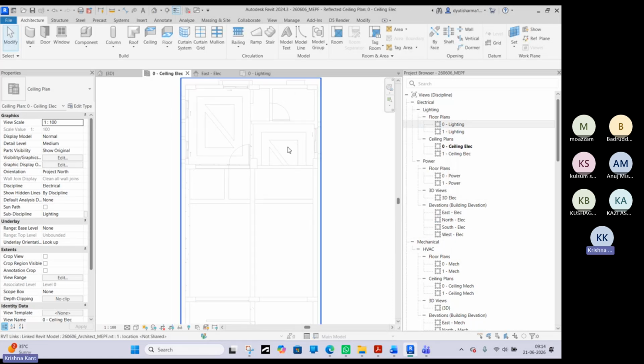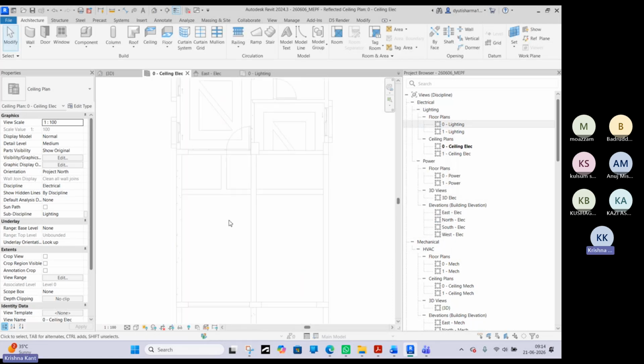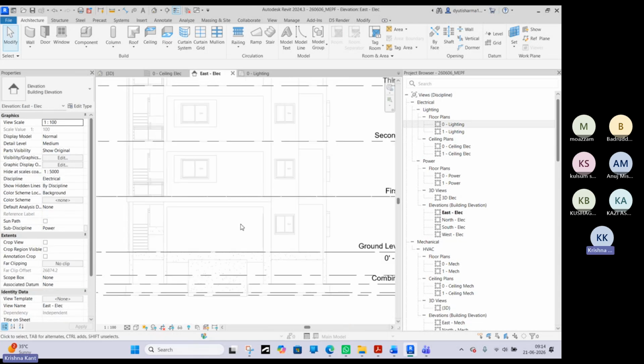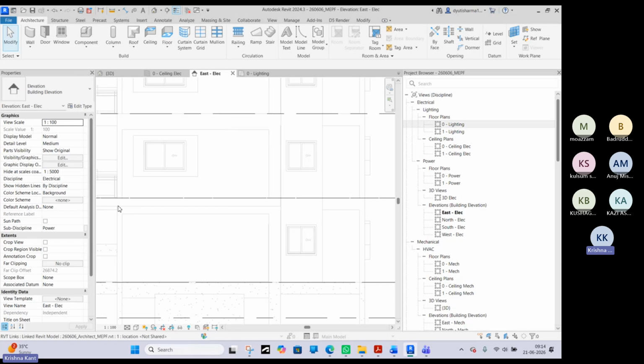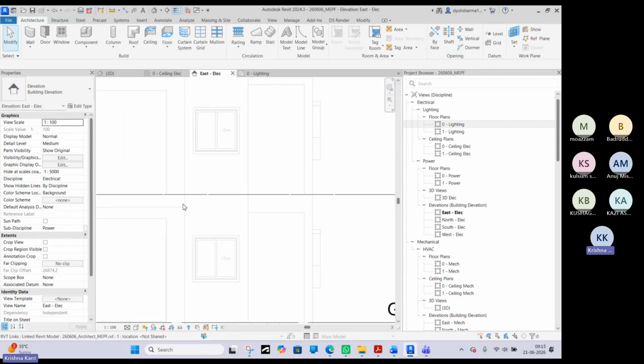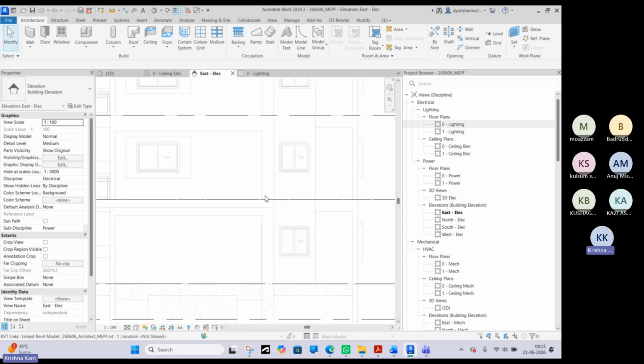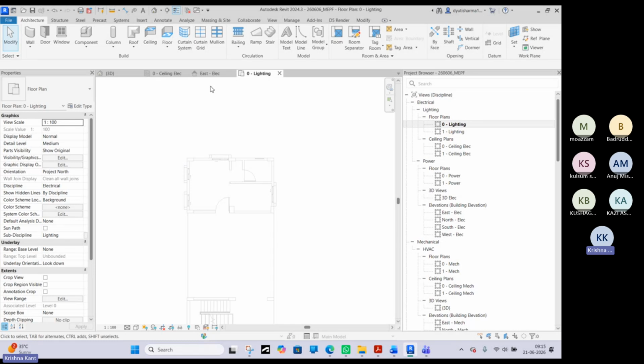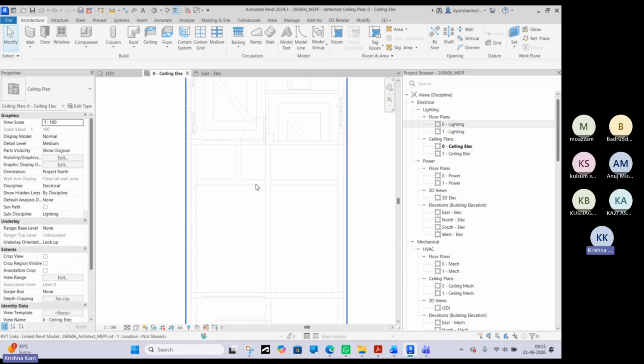Okay, now it's completely fine. We are not seeing the slab inside. We are seeing only the ceiling area and inside the floor. Okay, so right now if I go to the elevation, earlier the ceiling plan was somewhere here so that all the slab things are visible. Now we are just a little below. So right now we are somewhere here and we can see all the ceiling elements easily. Okay, understood? In the ceiling plan.